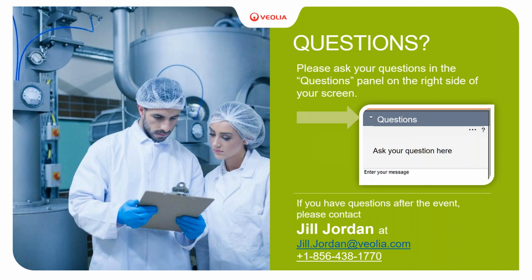And if you start to see like 10,000 milligrams per liter at level 8, you would want to take some sludge out. In our O&M manuals, there's a calculation on how to do that. But you want to take out at least a truck at a time.